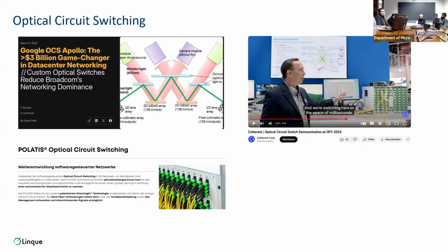Different ways exist, and then that micro mirror shoots the other fiber, and you adjust these mirrors to assign which fiber goes into which fiber. These are very bulky systems. They're also not completely energy free, and they're also very slow, but they are very low loss, and this is how they're being used.